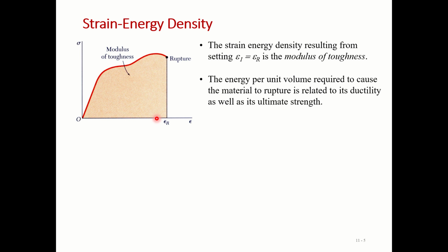So this modulus of toughness depends upon the ductility. Ductility means the span, the spread of this curve, and the ultimate strength. So it is related to the height of this curve. So the higher the height and the larger the span, the more this area will increase.